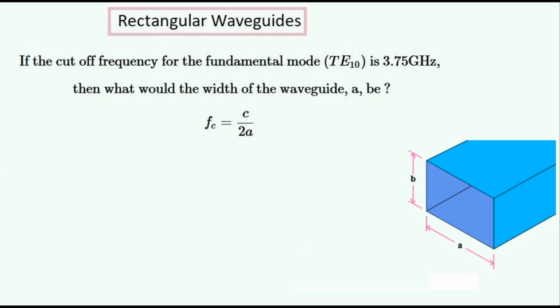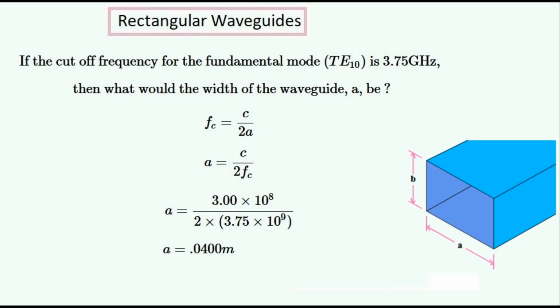This is the equation which relates the cutoff frequency of the fundamental mode to the longest width A, which is a designing problem. Manipulating this equation gives us A as the subject of this equation. Plugging the numbers into this formula gives us this expression, which will give us this answer to A in meters. And this answer can be written in centimeters. Waveguides usually have the value of A in this range.